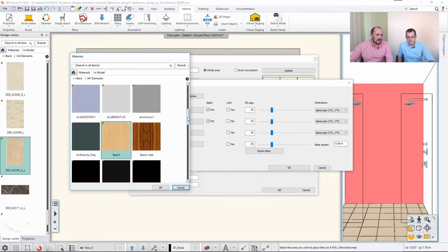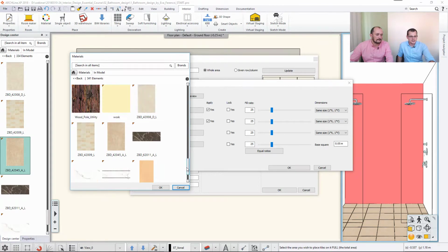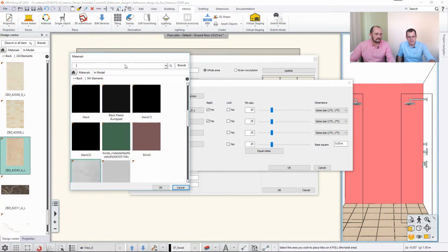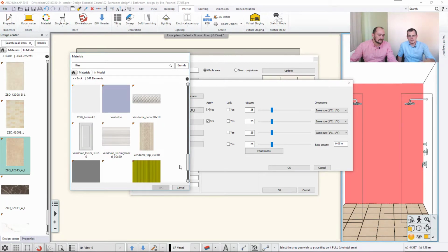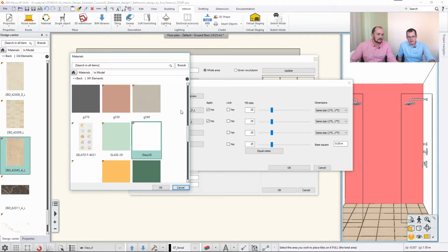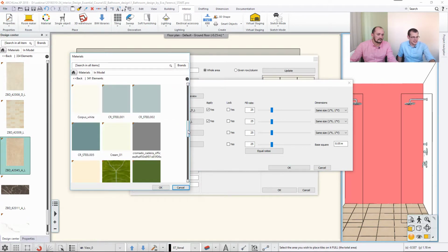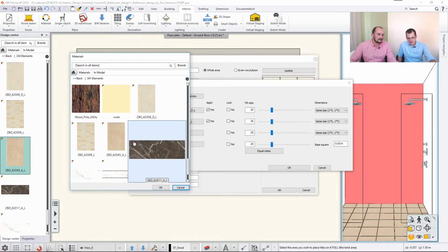In the meantime, I'm just quickly selecting the tiles themselves that I would like to distribute there. So let's just choose 3 or 4 different tiles. Even if the tile has a manufacturer size, it's going to be scaled down to a preset size that you are going to set up. Now, regarding the fill rate, like I said, you have a manual command on the distribution proportion. And once you do that, you just hit OK, and the program does one randomized distribution for you. If you don't like that, you can regenerate it anytime you want. That's one of the things that would take some processing power, but once it's done, you can just be on your way and work with it.